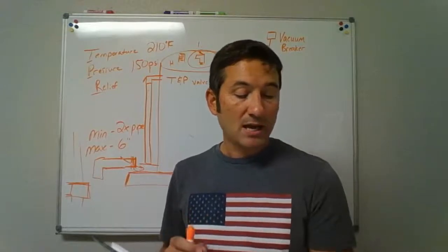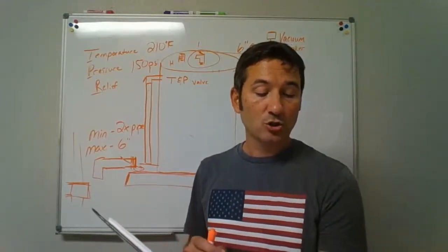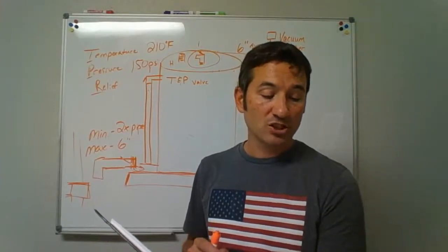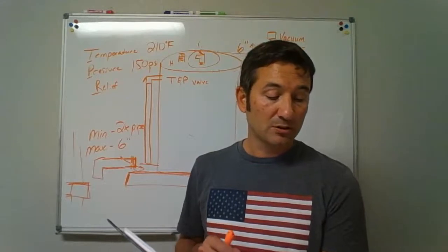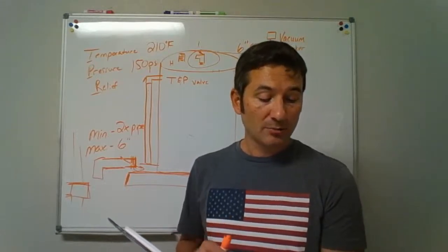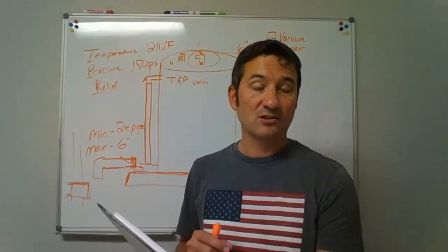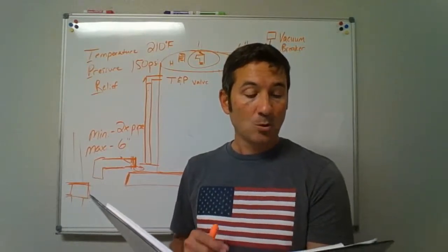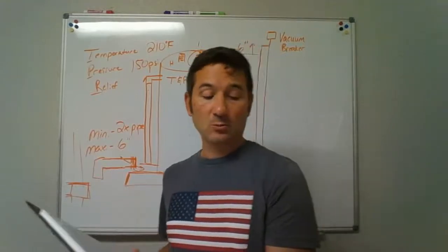Okay. The pan drain termination, 504.7.2. The pan drain shall extend full size and terminate over a suitably located indirect waste receptor or floor drain, or extend to the exterior of the building and terminate not less than 6 inches above and not more than 24 inches above the adjacent ground surface. Where a pan drain was not previously installed, a pan drain shall not be required for a replacement water heater installation.